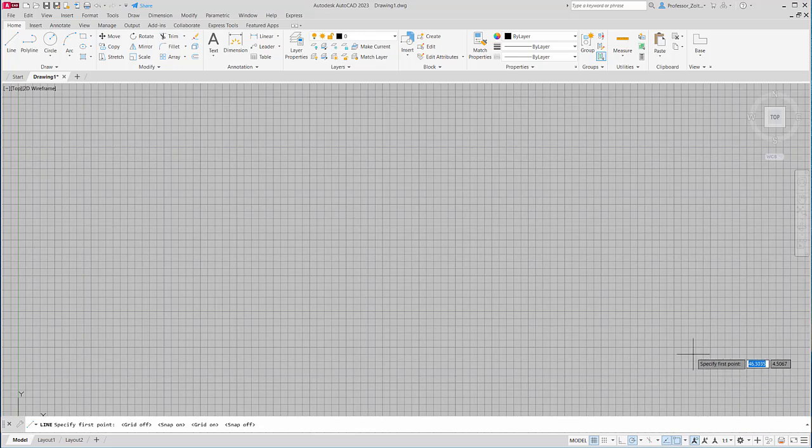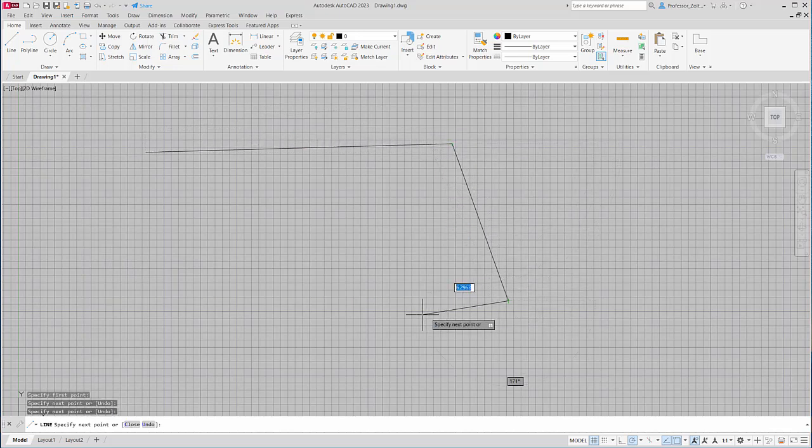Okay, so let's take a look at our drawing screen. And this is what's also referred to as the drawing editor. I must identify every step that I do within CAD for it to respond. So if I want to draw a line, I'll click on the line tool, and then I click on every position. So all I'm going to do is, with my left mouse key, click, and then click, and click, anywhere on your screen, doesn't matter. And you can see what's happening.